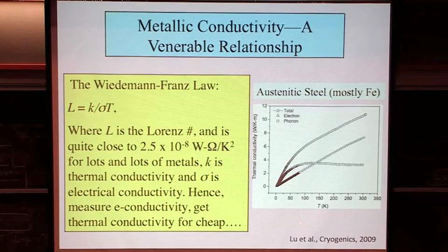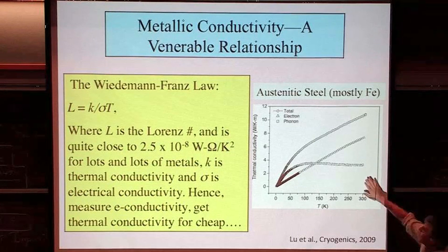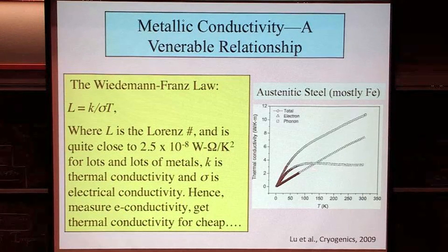We're going to return a little bit to thermal conductivity here, because of the underpinning basis for this. This is just from 0 to 300 K, and the trajectory continues on up here. This is actually the conductivity of a steel, very close to iron. This is the conductivity produced by the lattice itself, by propagation of thermal waves through the lattice. And this is the amount of thermal conductivity due to electron conduction of heat. You can see that this flattens out at about 100 K-ish and moves to very high temperature at about this level, whereas this keeps going and going.